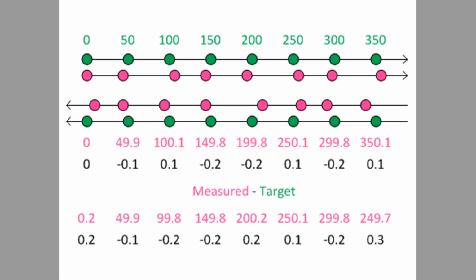This shows up more as a problem on rotary axes. The reason it shows up more of a problem on rotary axes is that, using an A-axis as an example, where we go from minus 90 to plus 90, typically before we started shooting comp with the rotary lasers, somebody had put a test bar in the spindle and they had swept the rotary axis so that we could verify that the rotary axis is properly aligned to one of the geometry axes.